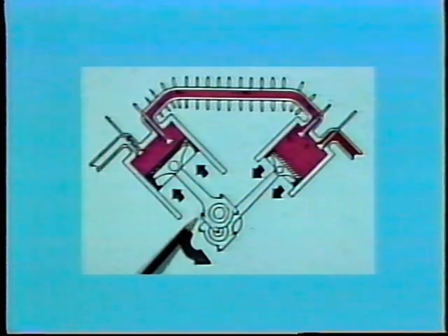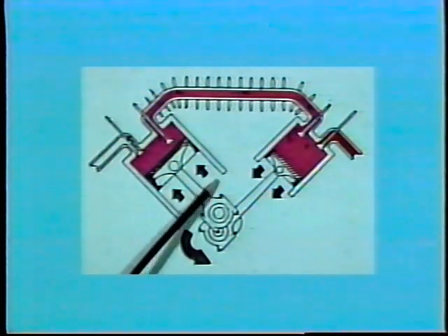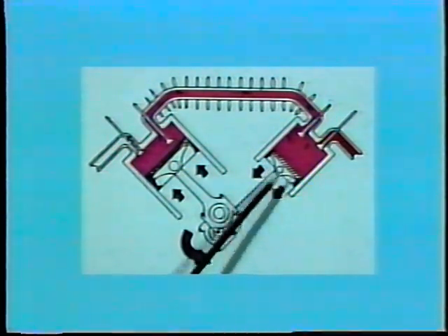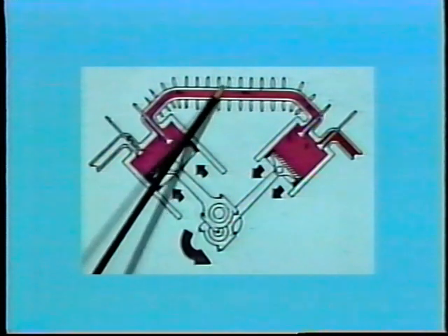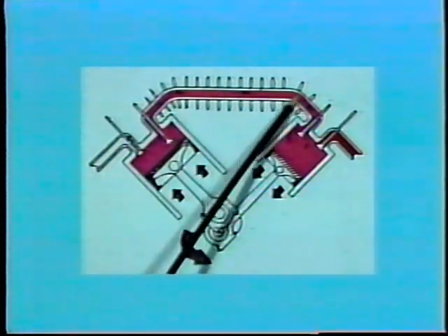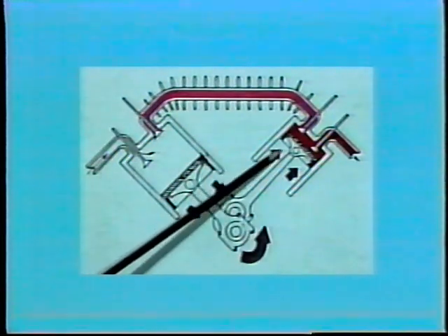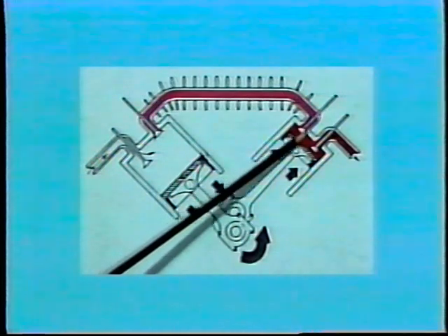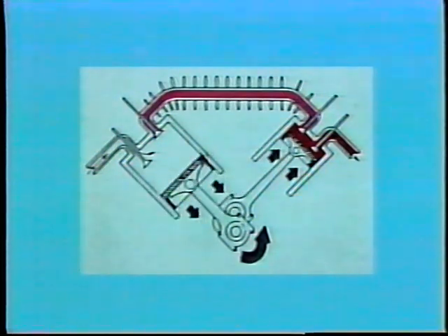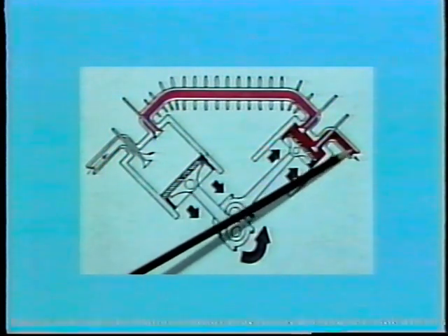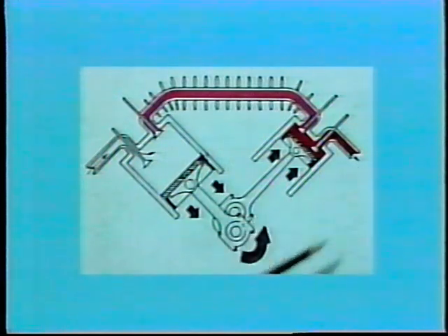The stages are interconnected so that when the piston in the first stage is moving upward, the piston in the second stage is moving downward, and its inlet valve is open. The compressed air from the first stage enters the chamber. When the second stage piston begins the upward stroke, the inlet valve is closed. Pressure builds, and when it reaches a high enough value, the outlet valve is opened, allowing the compressed air to discharge into an air receiver. This completes the second stage of compression.